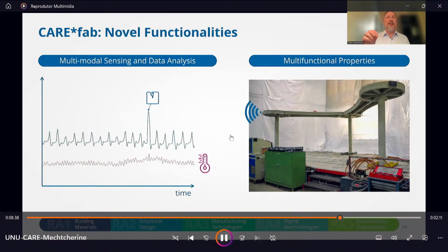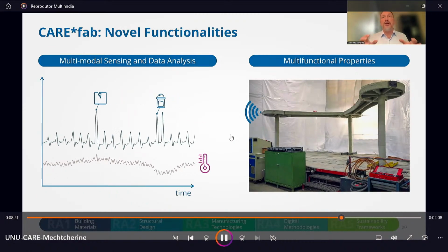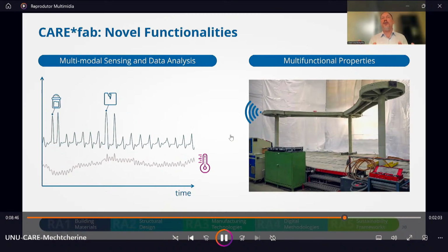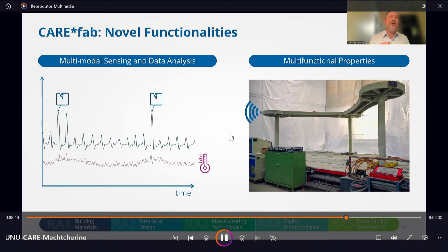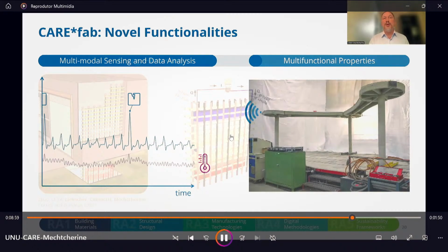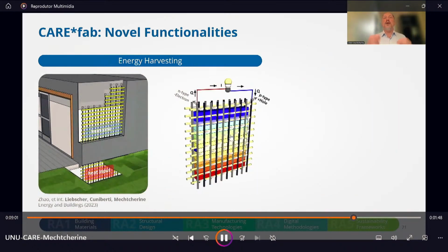By integrating sensing fiber reinforcement, the structural members will gain entirely new functionalities. Multimodal data collection in real time will enable machine learning models for predictive maintenance, detecting cracks, and monitoring ingress of critical media and salts. The sensors will be self-powered, utilizing thermoelectric energy harvested via the Seebeck effect. CARE will enhance the efficiency through chemical doping and nanomodification at the fiber level.